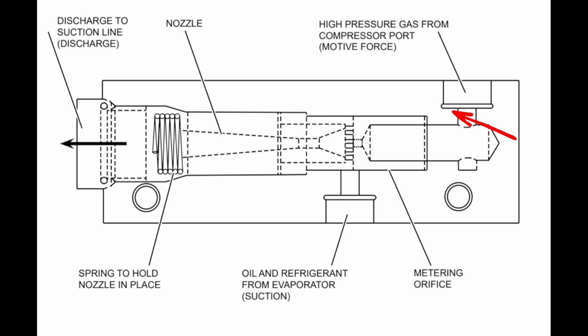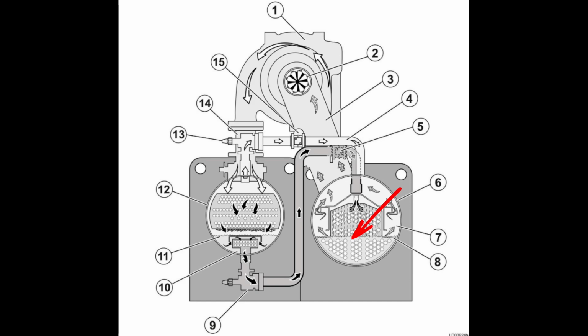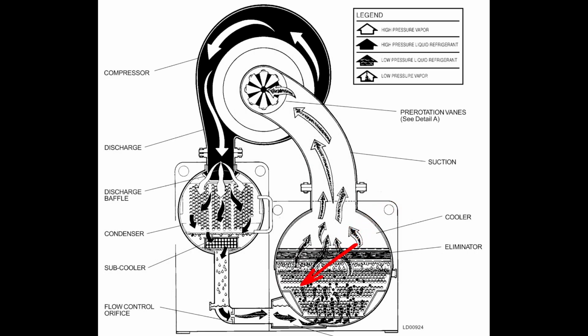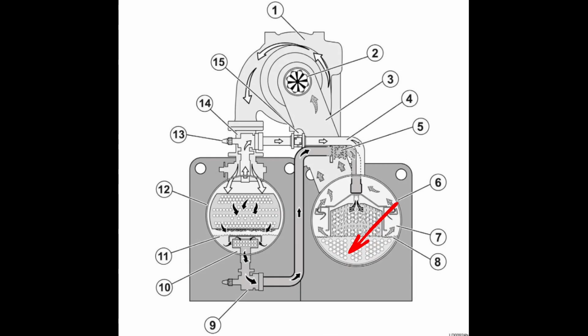So part of what we have to keep in mind is the oil. Because oil is lighter than refrigerant, it'll concentrate here at the top, typically, of that refrigerant. Now, depending on your type of evaporator and where things are set up, where that refrigerant line is can fluctuate heavily depending on your particular machine.